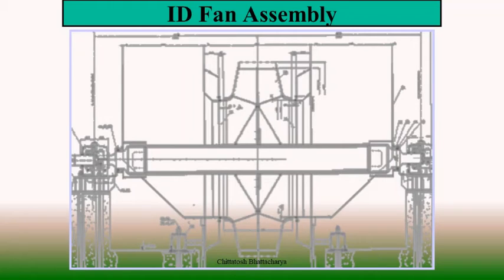The bearing which is away from the motor can accommodate the expansion of the shaft, and that's why non-driving end bearings are always free to move. Shaft is free to move through this non-driving end bearing. So this is also called non-located bearing. Motor side bearing is called located bearing, and it is fixed in position.